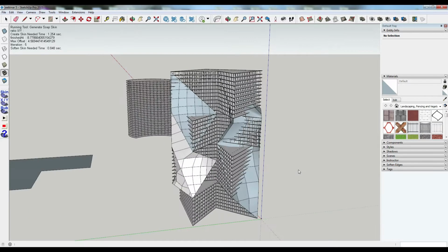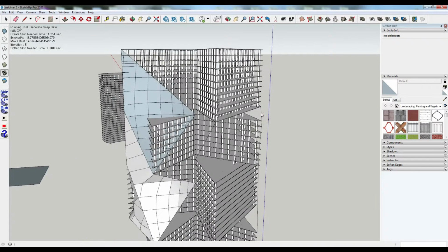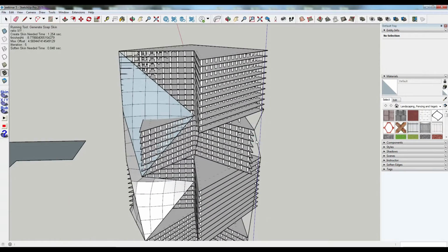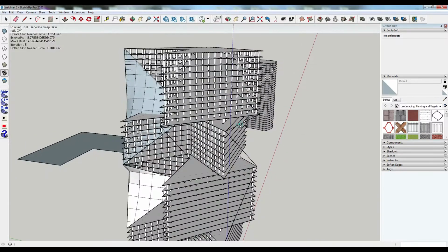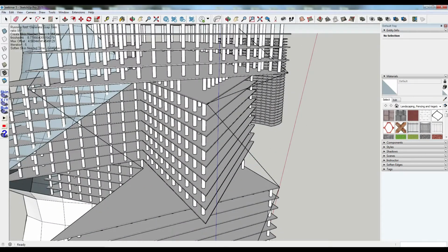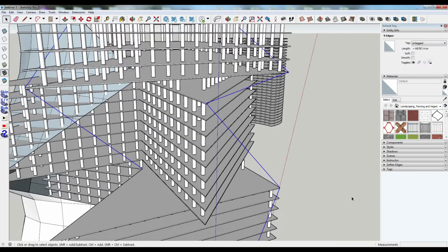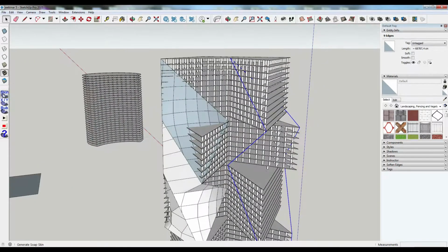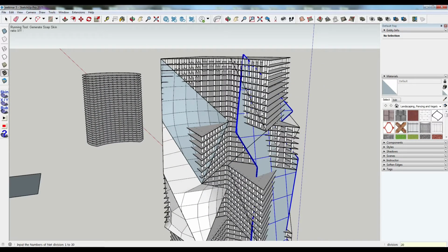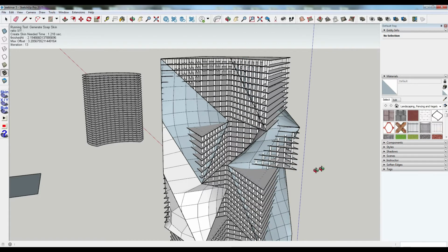I will demonstrate the fastest way of working when I make the contouring with the lines. I could triple click with the left button of the mouse, then just pressing skin, and now I will make a bit more detailed surface, so giving 20 by typing it on the keyboard and then pressing enter.